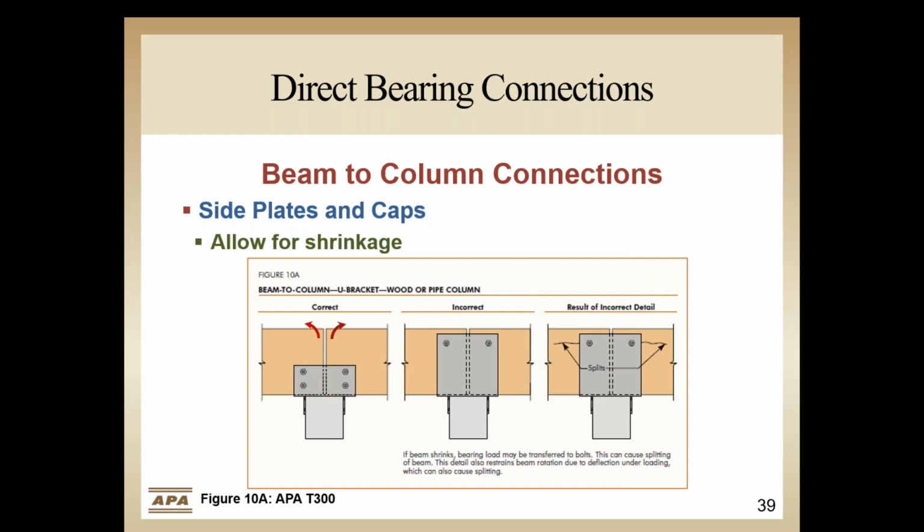Beams supported on columns aren't much different. Provide full bearing and a connection that allows the beam to move. However, in this example, the only movement that we need to consider isn't from moisture. Loaded beams will rotate at the bearing as a result of the deflection of the beam, so the designer should consider this and detail a connection that allows for this rotation.